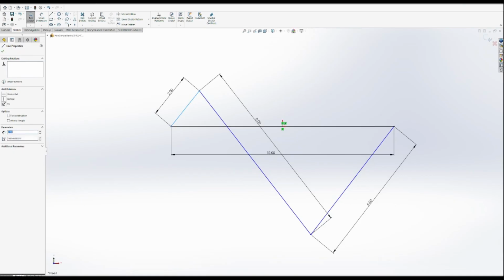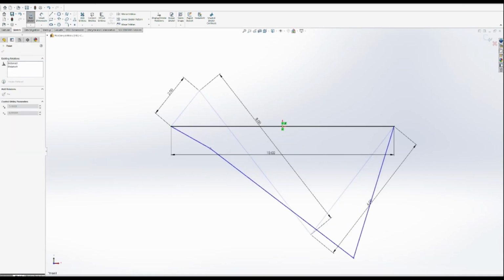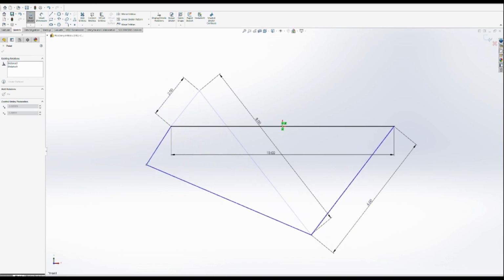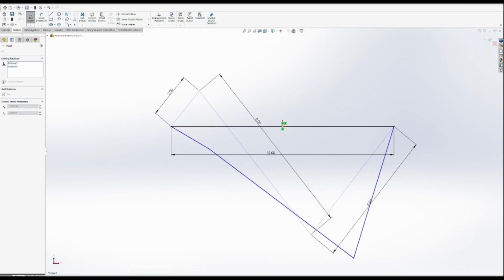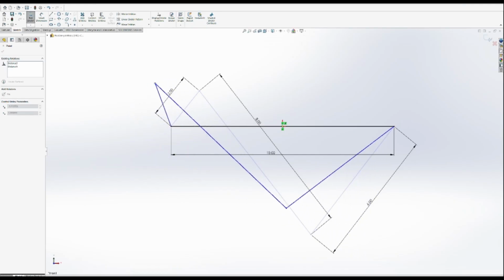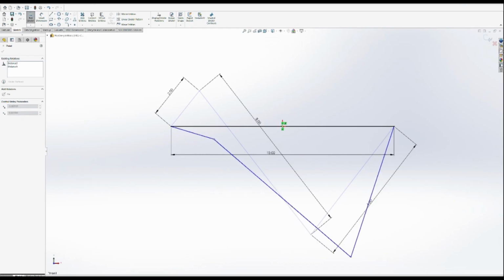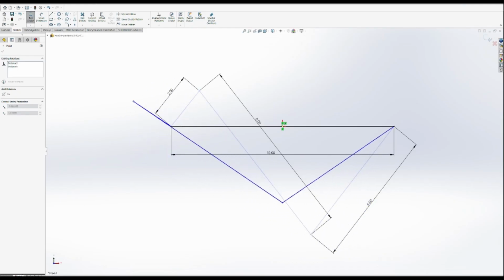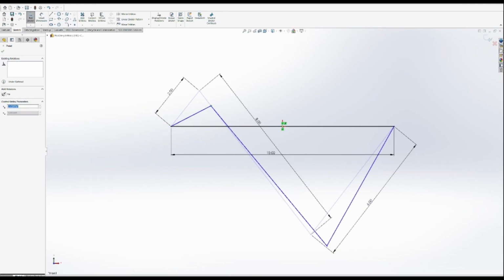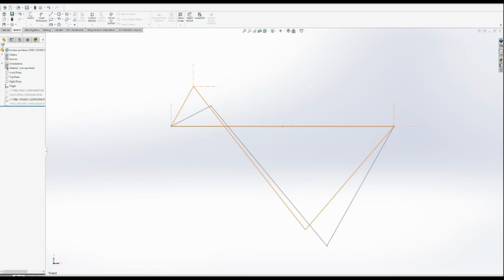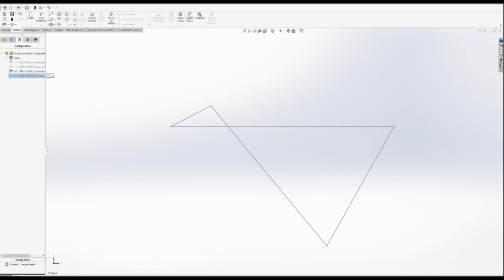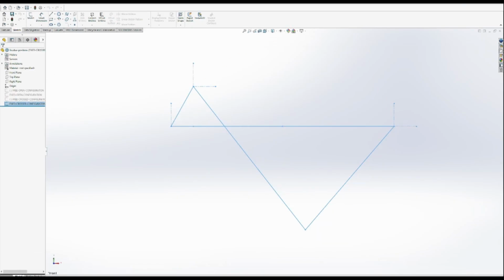And as you can see, it is still a Grashof linkage. The input link can still make a full rotation relative to the other links. But now you've inverted it about the ground link. But in many ways, it is a very similar linkage. But this is now the other solution associated with the quadratic solutions of the parent equations that we saw earlier. So with that, let's see if we can replicate the results from the parent equation. So let's go to the last configuration here, fixed cross, and let's go into the sketch.